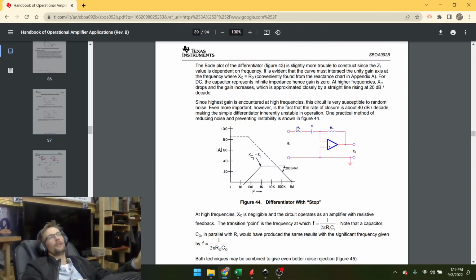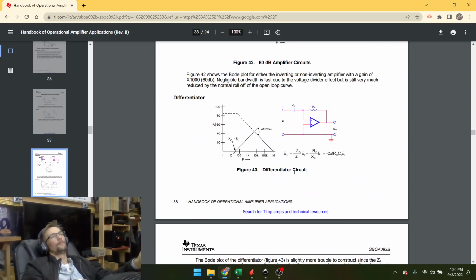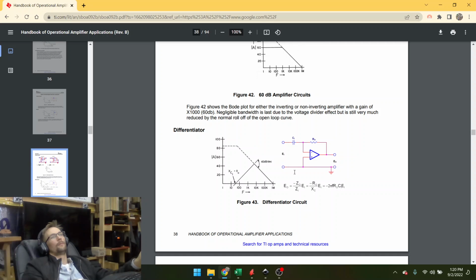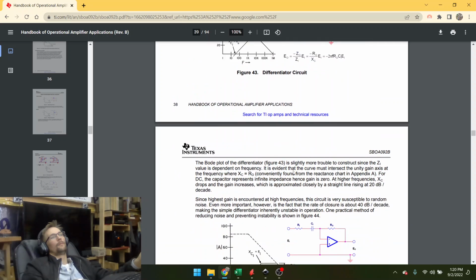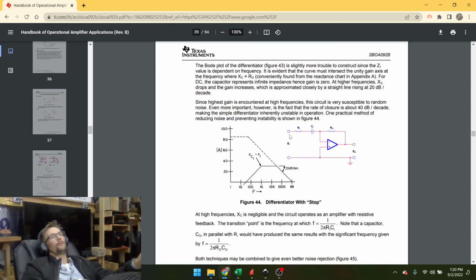But you can put this guy here, and then the parasitic resistance there, which would have taken it up a little bit more, but then you'd have variation piece to piece. Where you put this guy in, the tolerance on this is real precise, and then you can precisely hold it. And then the variation due to the parasitic resistance in your capacitor will be combined with that, and it won't affect it as much. Gotcha. Okay, cool. That's cool. I like that.